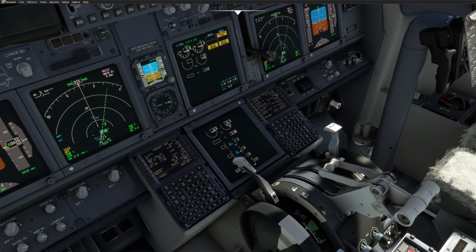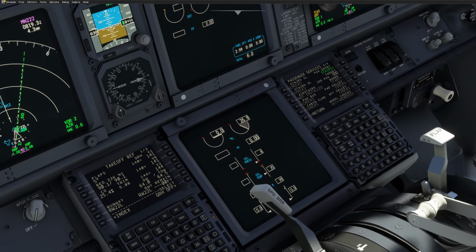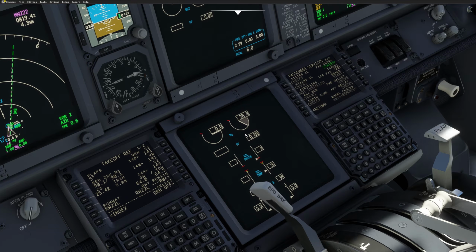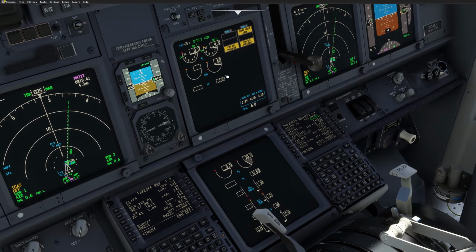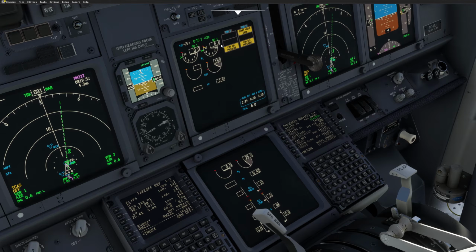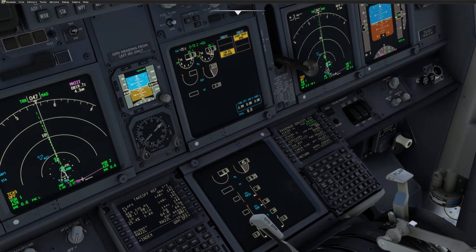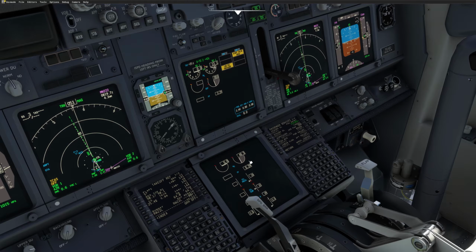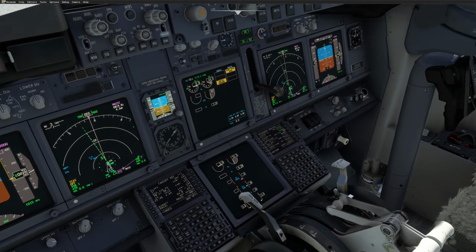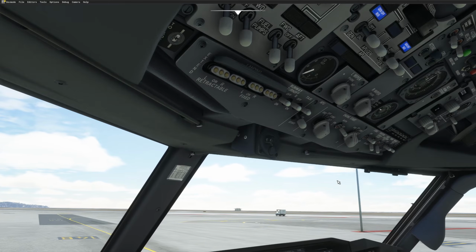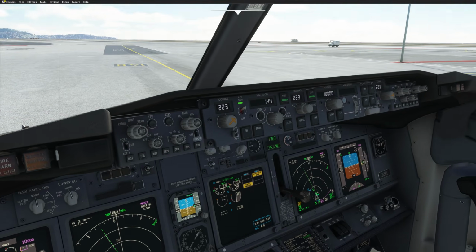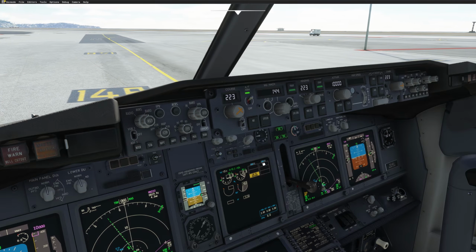So when we put the fuel on, just now, what we expect to see is a fuel flow. Once you have a fuel flow, ignition is there, we should have a light up. Now that we have a light up, we continue to monitor N1, N2, and oil pressure rising. When the value is above 12 to 13 psi, the low oil pressure light goes away. We continue to monitor everything, and we are waiting for 56% N2. When you have 56% N2, the switch will go off, and that light will go. This is what we are looking at.